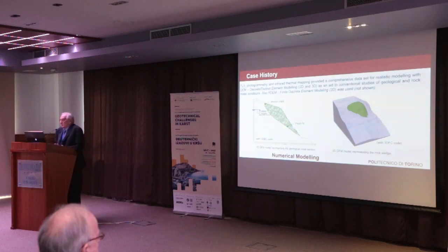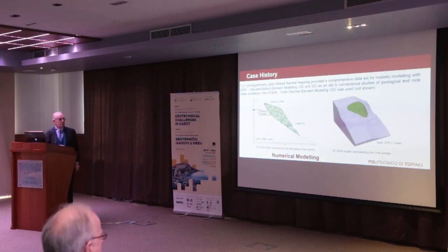I say it is a realistic two-dimensional model because it is based upon quite a lot of data that I've been able to provide: in situ investigations, high quality in situ investigation by using terrestrial laser scanning, photogrammetry. You remember laboratory data, borehole logging. We also had inclinometer data, ground-based technology that allows us to check.